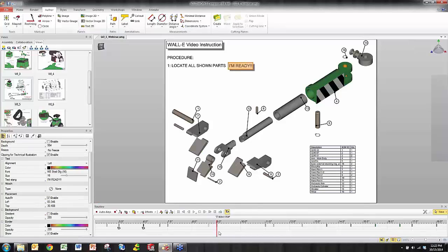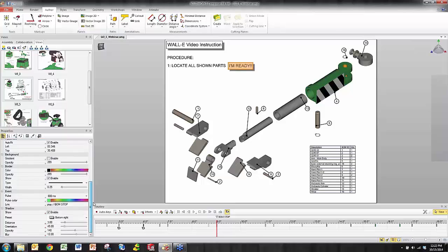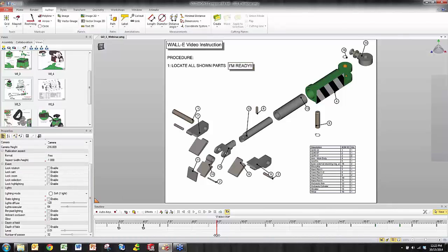So I'm going to highlight this again. I'm going to highlight the components that I changed, and I want to make sure that those are present the entire time. The link, yes, but the pulse, I want to start right at 9. So I'm going to leave that one out of this. And I'm going to come up here to set as neutral property. When I do that and move my time bar backwards, you'll notice it fades in with all of those properties intact.